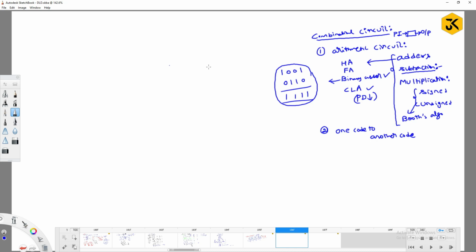Meaning we can get addition as well as subtraction with the help of a single circuit. That is what I call the 4-bit binary adder or subtractor. So I can perform binary number addition either through the purely binary adder circuit, or through the 4-bit adder or subtractor.